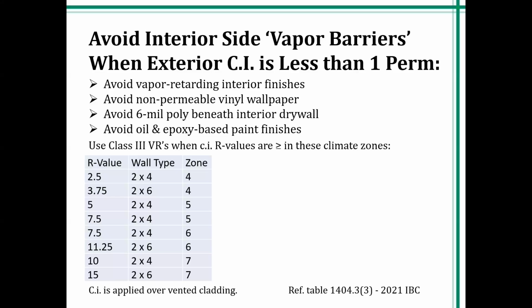We have a clean room drop ceiling, and say you have slab to deck heights of 10 or 12 feet, and the interior space is maybe 10 feet, and you have another 2-foot plenum above the ceiling. It's not likely that the plenum area is going to have that epoxy paint. Also, if the framing happens to be steel framing, or for that matter, CMU, steel framing, of course, has all those little knockouts. And we have outlet boxes and switch boxes.